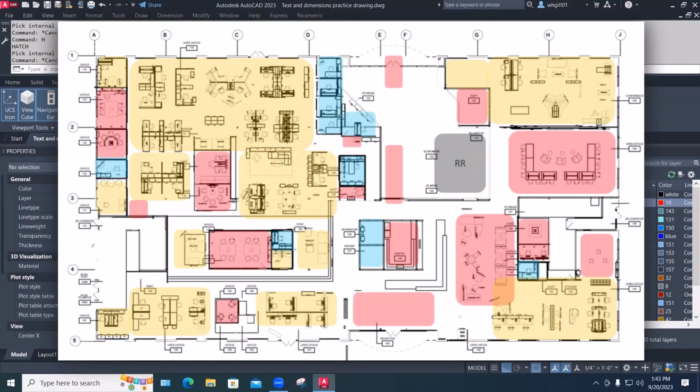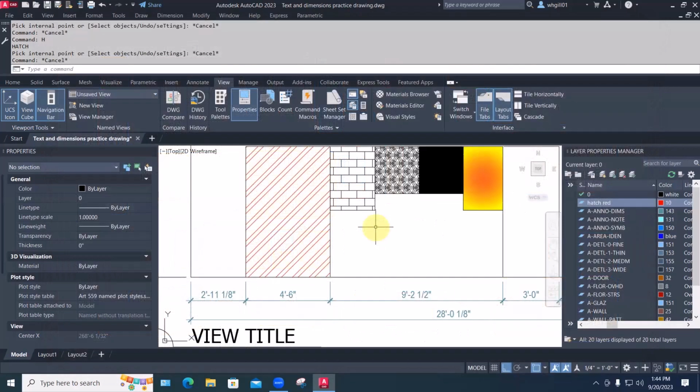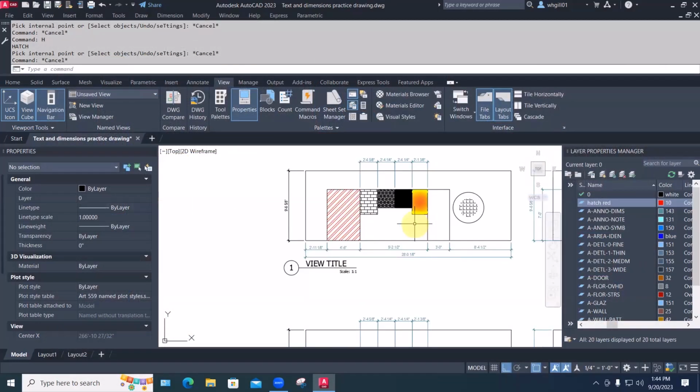And then there's something I'm calling graphic emphasis for planning or presentation purposes. You might want in a floor plan of an office space, for instance, to have all of the manager's offices with a light green background and all of the secretarial offices to have a light yellow background and the bathrooms a light blue background, something like that. So it's really clear how those areas relate to each other. If you've got some management here and some management here, it's really easy to see if they're separate colors. You might realize, no, I'd really rather move them up together. So it helps the client and you understand either what they have or what they're getting. Creating a hatch always starts with some sort of bounded area.